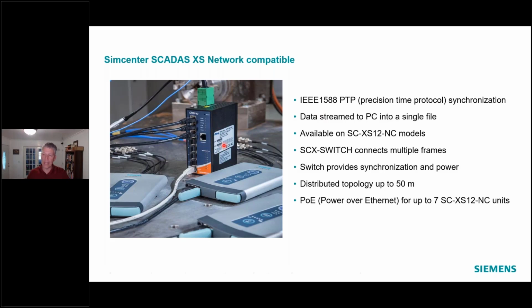This doesn't work for just any switch you could go buy off the shelf because it needs power over Ethernet. That's pretty easy to find nowadays, but the IEEE Precision Time Protocol is pretty unique in a network switch, and it has to be configured specifically to work with the SCADAS XS.